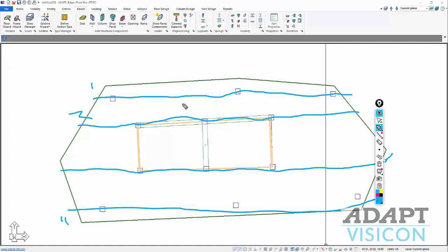In this case, we do not want this to extend into the ramp, and that might lead to geometry. If we look at a section cut this way, that might lead to geometry where we have the upper slab and then the ramp slab. And when we combine this plus this into an idealized section, we may actually get something that looks very deep like that. It's just a solid chunk of concrete.